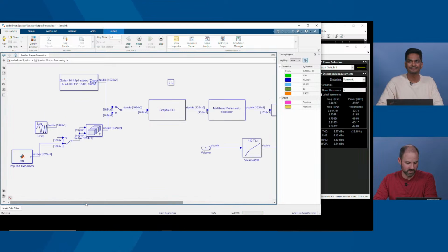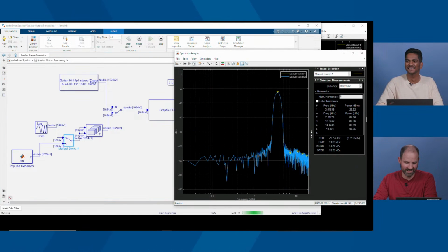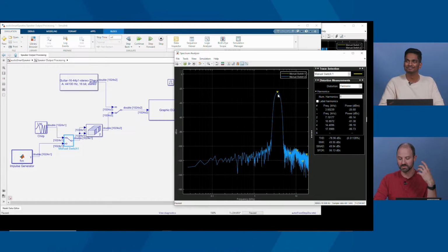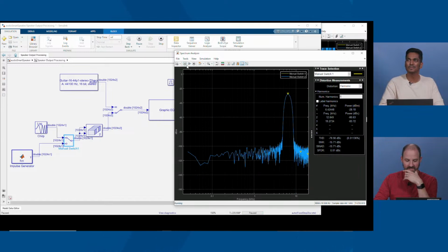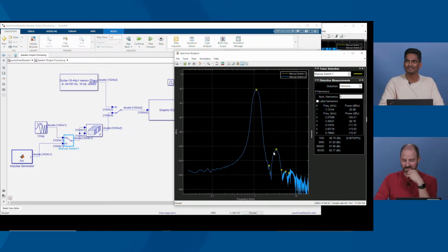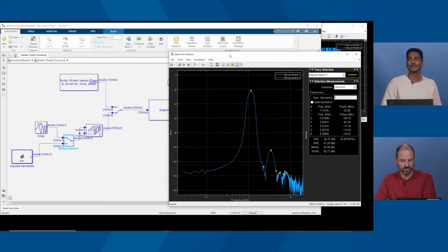You just reminded me, we have a chirp over here. So I'm going to flip on the chirp. It might be a little louder, sorry. It's not pleasant to listen to, but now I can visualize that measurement more accurately. Like I said, it's the ratio of the harmonics to the fundamental. Let me see if I can pause it. There we go. The fundamental is obviously our big spike here, and the harmonics are these little guys over here. The spectrum analyzer block is what you would use when you want to pick out frequency information of the signal. It just does a good job with that.